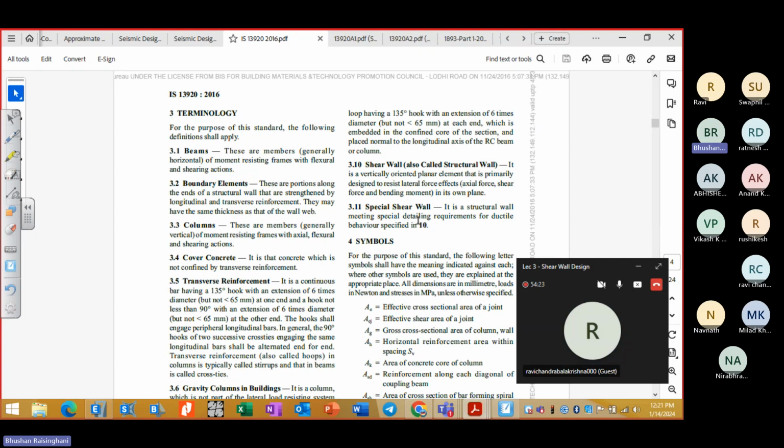I think SAP 2000 does not have that feature because it is purely finite element software, and by default it divides the element into small pieces. If you provide a restraint, your moment will be generated at the restraint, that is, in the reaction that we get. In one article I found on the net, it said the in-plane moment forces are included in the F22 forces.